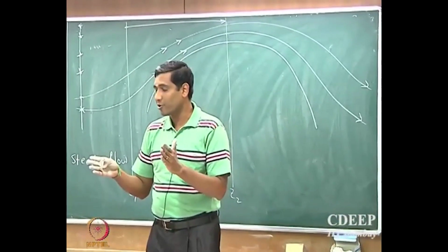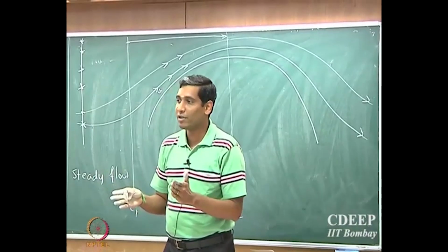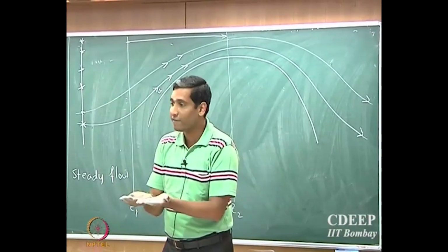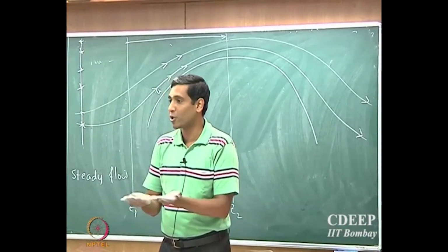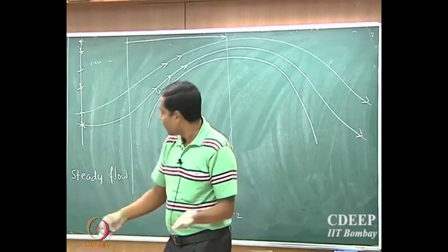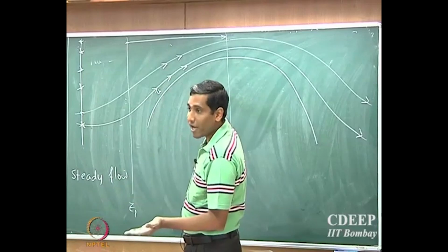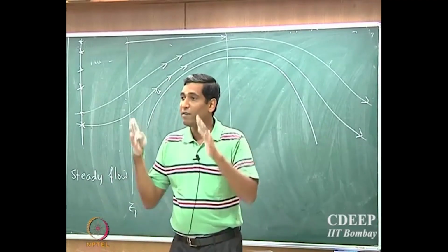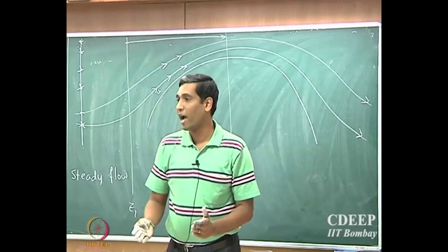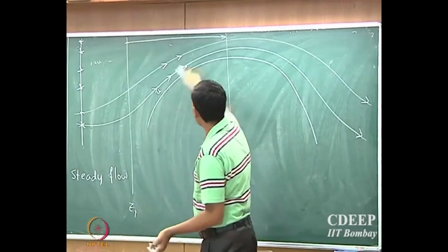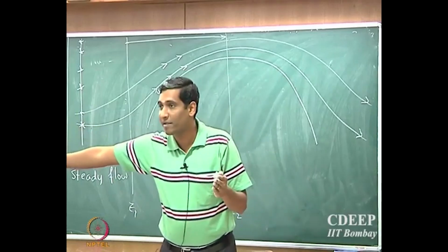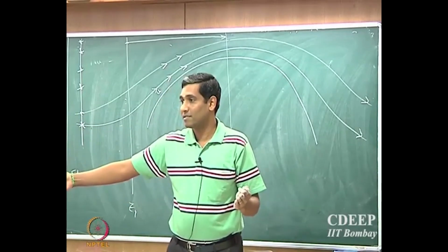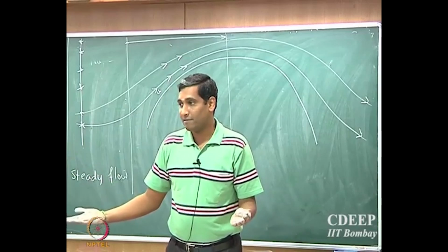The velocity difference that you see in a flat plate is because of the friction that the fluid experiences because of the presence of the flat plate, and you will see the same thing here in a short while. But even if you have friction, with this cylinder, in order for the fluid to leave at the same time, they have to catch up. But that's not true in a flat plate.